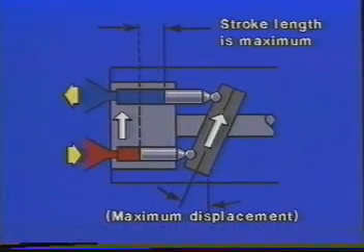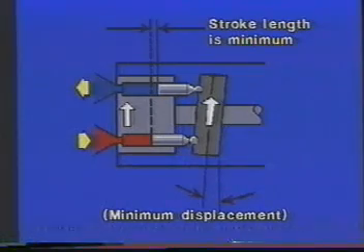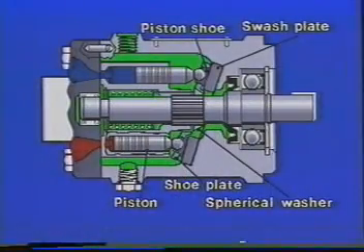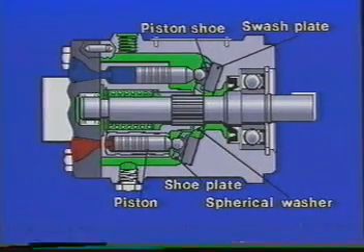A large angle and long stroke gives us high torque and low speed. By going to a smaller angle, we develop a lower torque but a higher speed. If we have a fixed displacement unit, we could have constant torque with variable speed, the speed depending on flow rate from the pump. Here, we have a more detailed view of a fixed displacement inline piston motor.